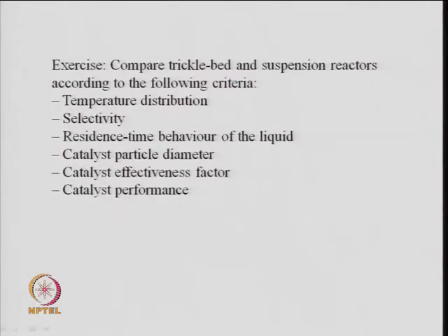There is another problem: compare the trickle bed and the suspension reactor depending upon the criteria. That is, whether you will go with a trickle bed reactor or a suspension reactor. Study this based on what you have understood so far: temperature distribution, selectivity, residence time distribution, behavior of the liquid, catalyst particle diameter, effectiveness factor, and performance.